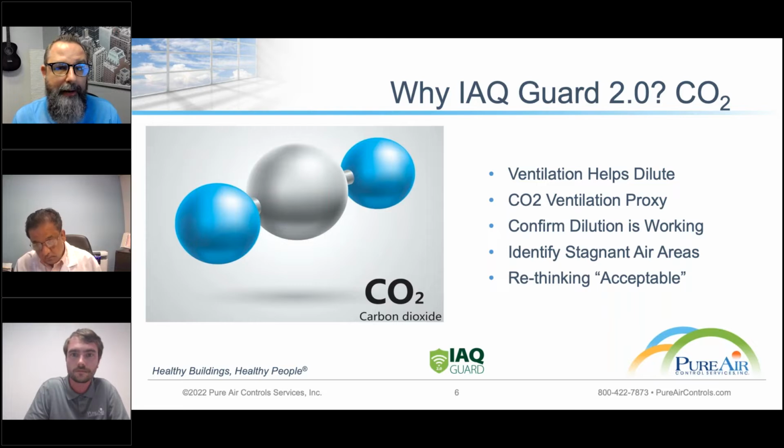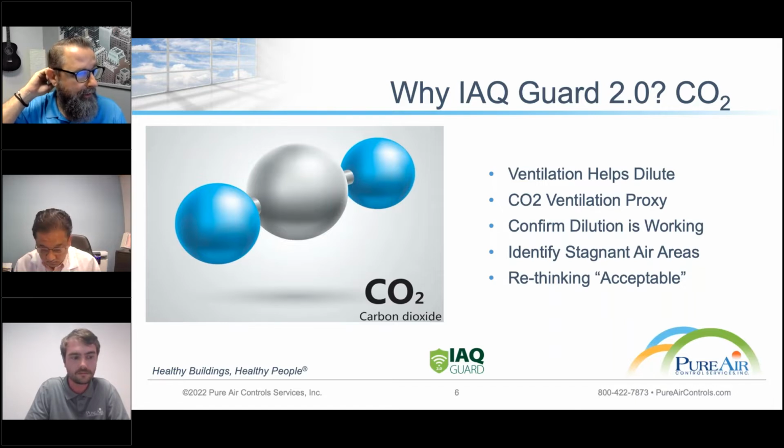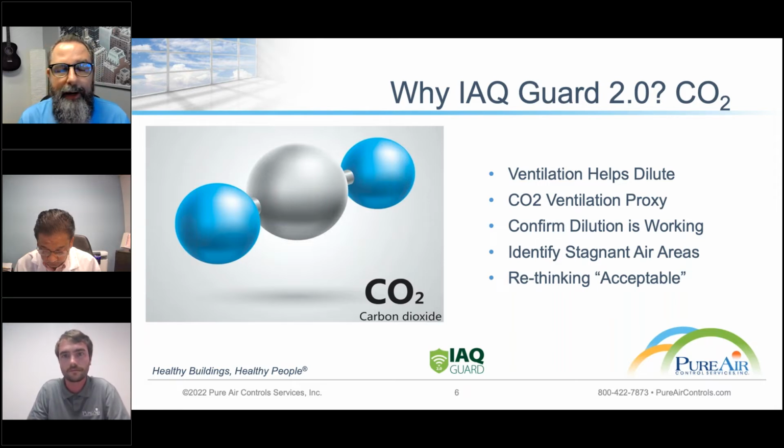Another thing that we look at that's very important, and we've covered this in past workshops, is CO2 as a contaminant of concern, or as ASHRAE is now calling it, a design compound, because we look at CO2 in various ways to help understand the ventilation in a building. And as we know, even up to and including today with the new White House recommendations being outlined for indoor air quality, ventilation is still playing a very big role in keeping buildings healthy.